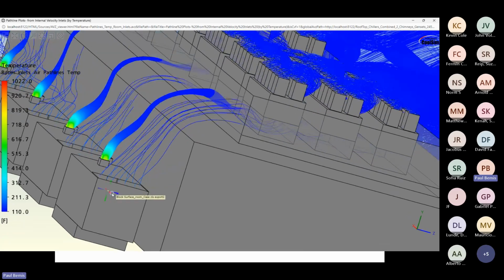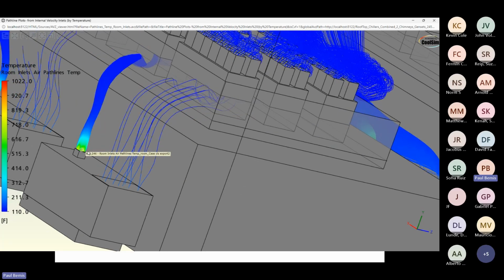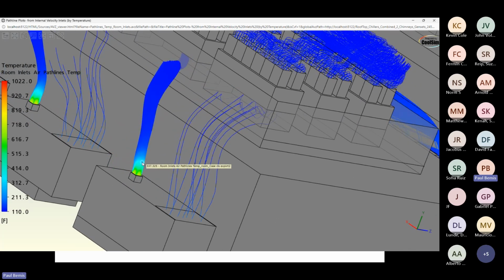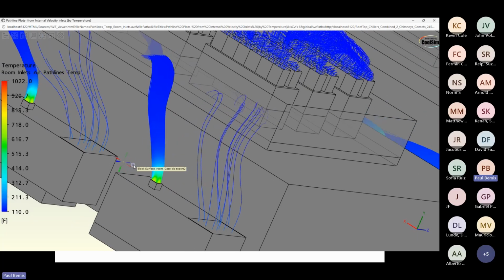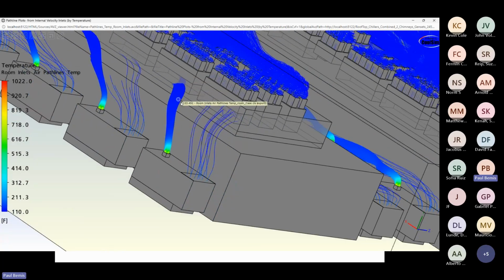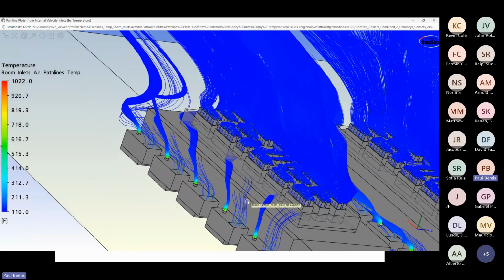So the general heat coming off of the heat exchanger itself is not generally that bad. You have some of that. So this is temperature running in the range of a couple hundred degrees Fahrenheit coming off there, 180, 200. These are running at like 900 Fahrenheit or 1,000 Fahrenheit, depending on the situation. I mean, fossil fuel burns at 900 degrees Fahrenheit on exhaust. It's typical 950, 980, sometimes 1,000, depending on the situation. And you see that exhaust is getting entrained into the intake of this chiller. Not a good thing. Under this wind condition, by the way, again, wind conditions will vary.